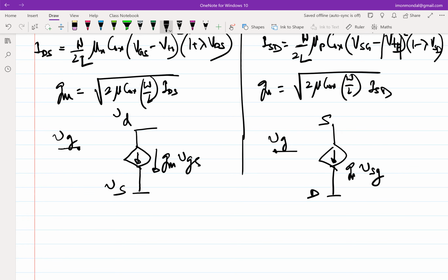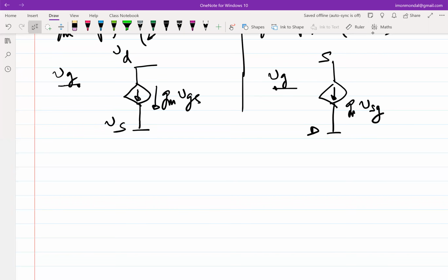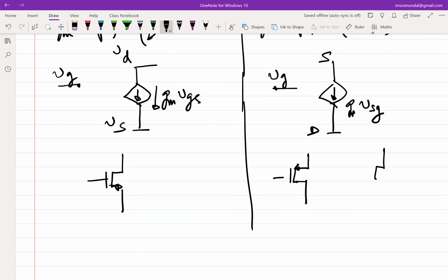Because ultimately, in case of a PMOS, let me also draw the symbols. There are a couple of symbols used to mark a PMOS. The one that I had already used mistakenly earlier has the arrow pointing inward towards the gate, just to show that the current direction is as shown. But there is also one more symbol, which uses a bubble. Typically this bubble symbol is used when you are using PMOSs in digital circuits, but it doesn't really matter. You can use either.